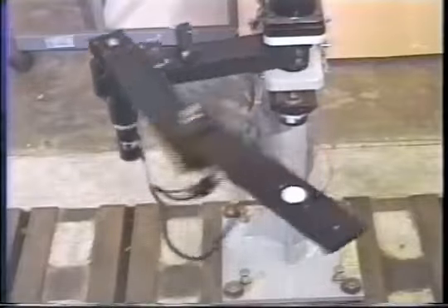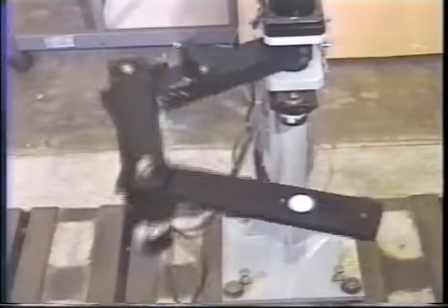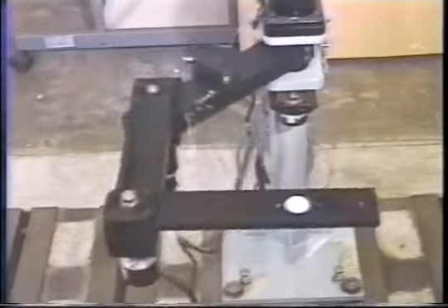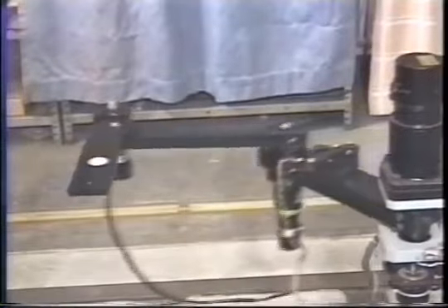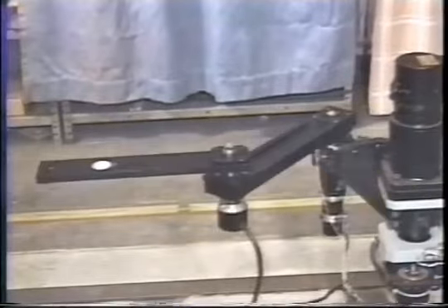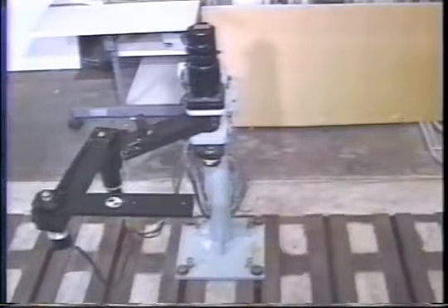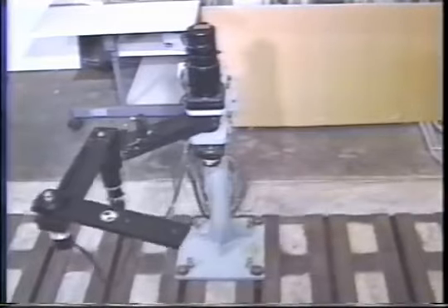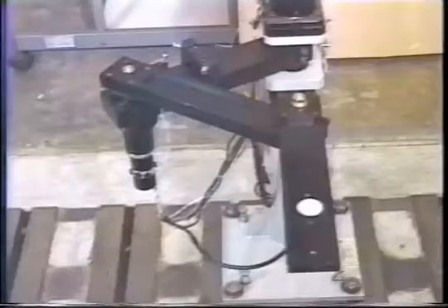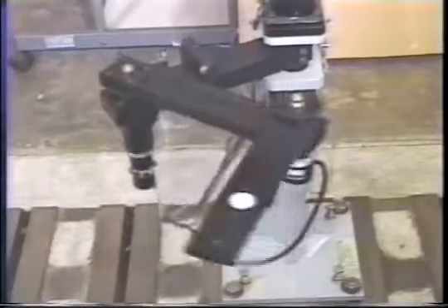The center of percussion of the link stays still if the joint follows a circular trajectory around it. The link can rotate without translation. This trajectory is also stabilized by feedback control. Without feedback control, each trajectory is not stable. The link deviates from the trajectory as shown.